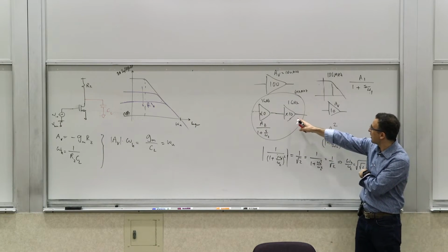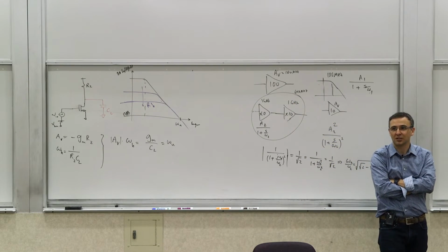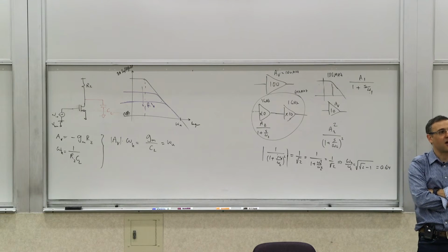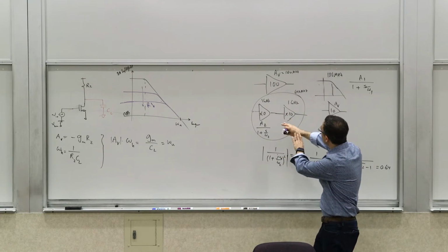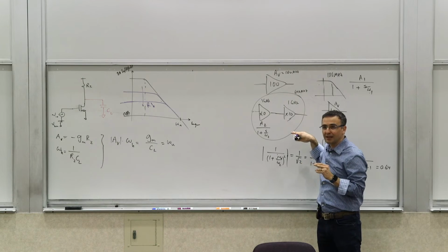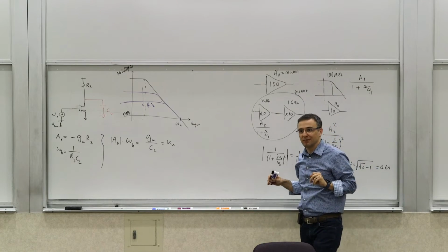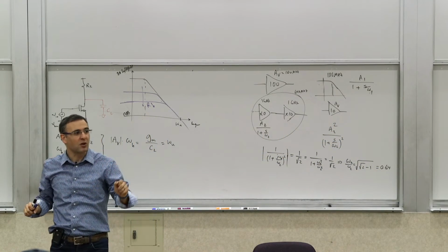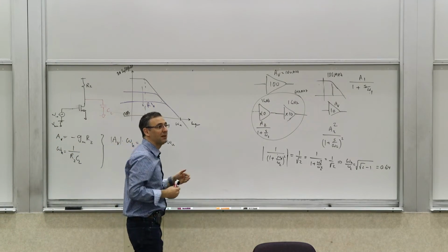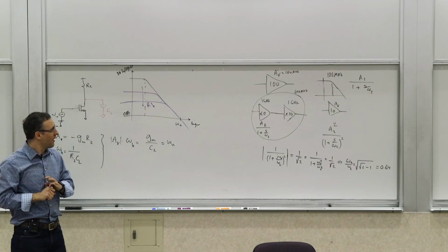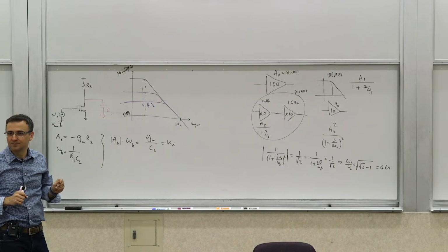It's because it seems that our gain bandwidth product has significantly improved, right? Because the gain is the same, but the bandwidth is more than 6 times larger. So that's why we are playing with that trade-off. We are trading delay for that. There's another thing: if this amplifier is to be used as is, in open loop like this, no problem. You can use it this way, and this works. But if you are planning to put things in a feedback loop, you're making the dynamics much more complex. And then we will see that these kinds of complex dynamics will significantly affect the stability of the loop and things of that sort. So as an open loop amplifier, yes, the price you're paying is the delay, possibly more power. But primarily delay.